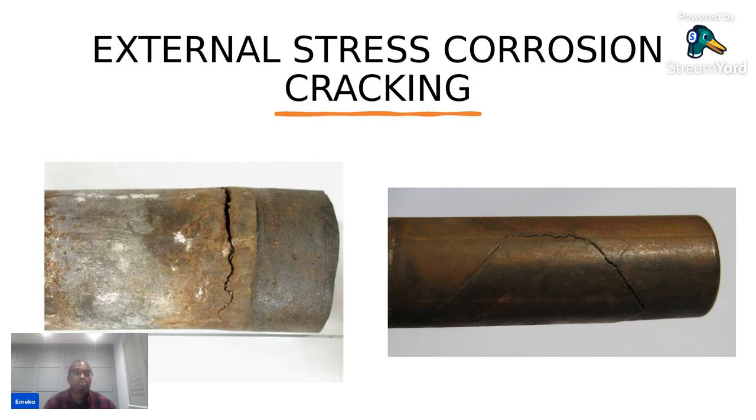It can be obvious to people who know how to inspect this type of material to find that the material has microscopic cracks, in order to detect that stress corrosion cracking is happening. So where does this occur? Stainless steel equipment and pipelines are susceptible to stress corrosion cracking in chloride-bearing aqueous environments, in seawater handling systems, submerged or in marine atmospheric conditions.